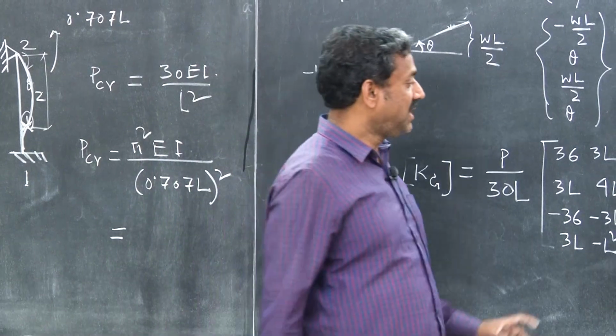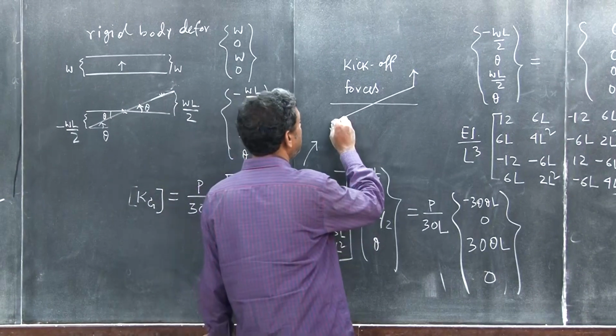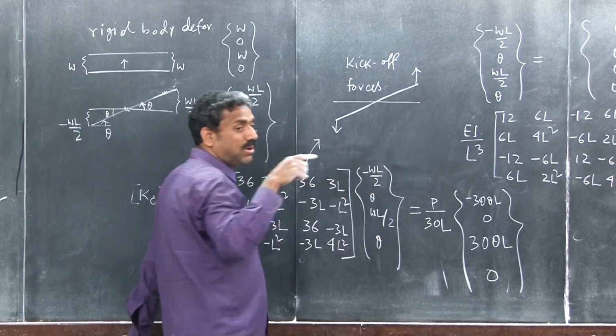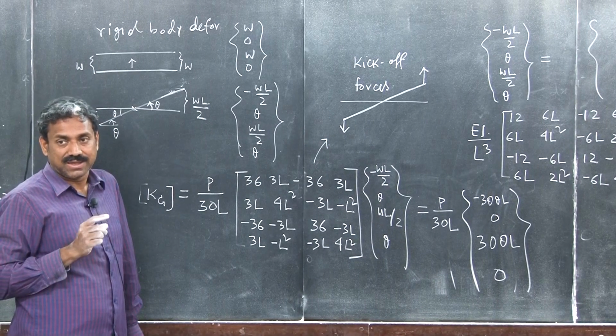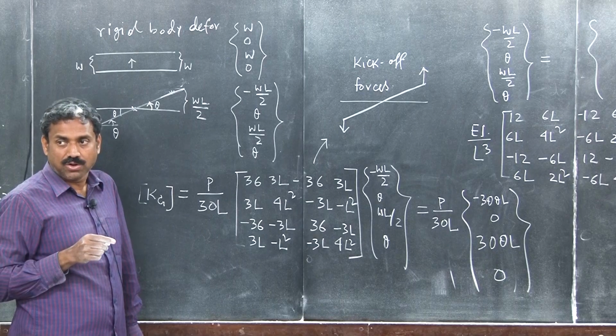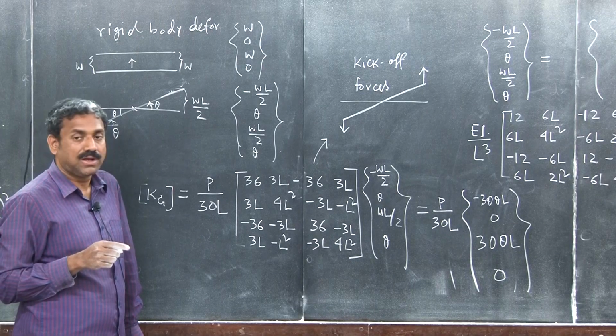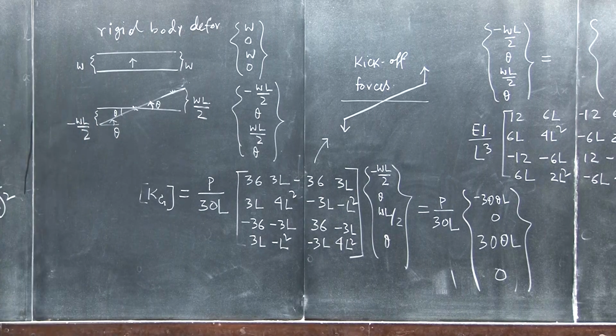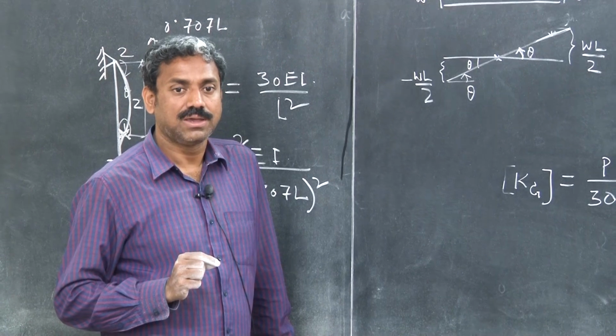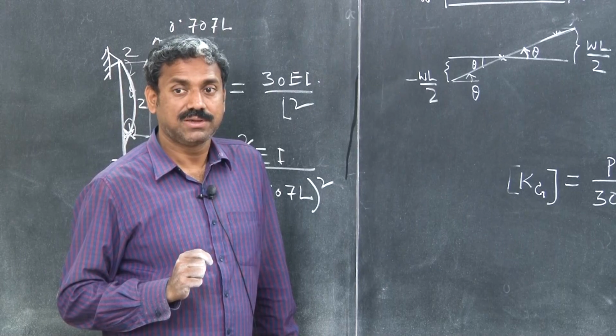See, what is happening is that when we are considering dw dx square, that means because of the von Karman nonlinear term, whenever del w del x is there, it is basically incorporating it. It is unable to distinguish whether this is due to rigid body mode or due to the elastic mode. You understand? Okay. It is unable to distinguish.